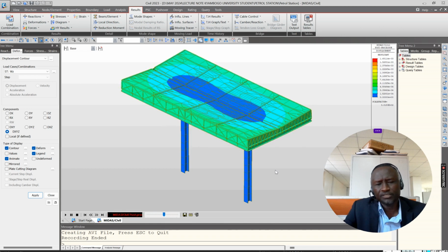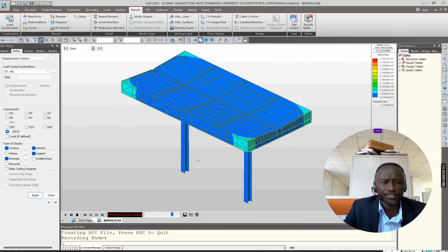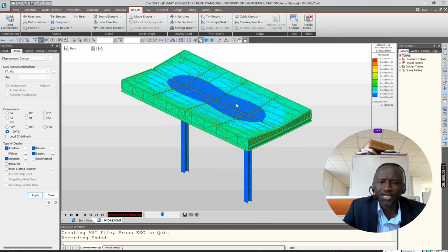The two main connections, the one between the column and the truss system, and then the one between the column base and the stub column, which is the foundation. That is something you have to take note of. Very, very important. Of course, there are these smaller members that will be failing locally, but globally, that is what you need to do. And once the connection between the truss system and the column fails, then wind will lift the thing up, overturn it, and the result may be catastrophic. You need to take note.